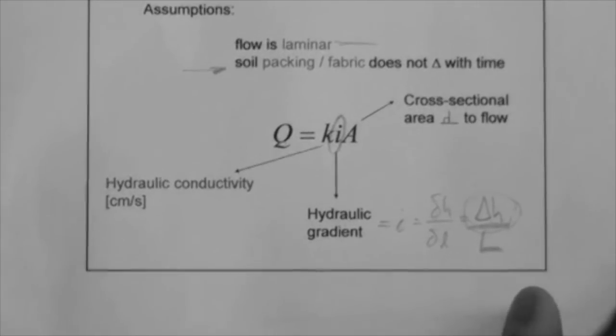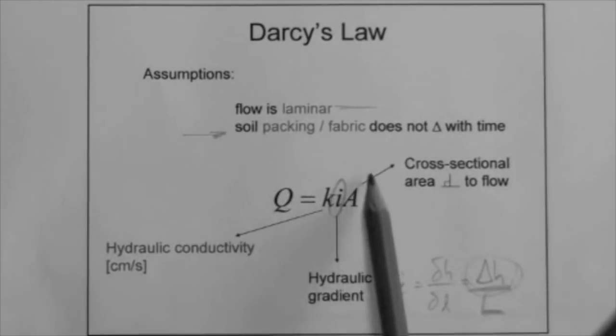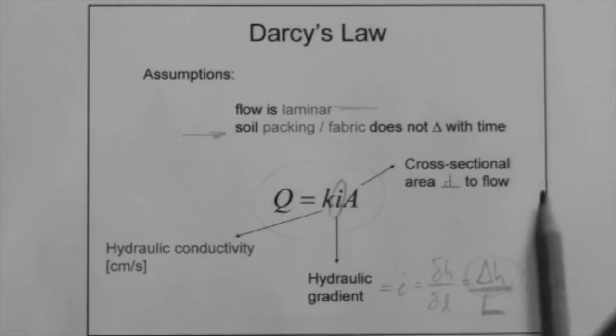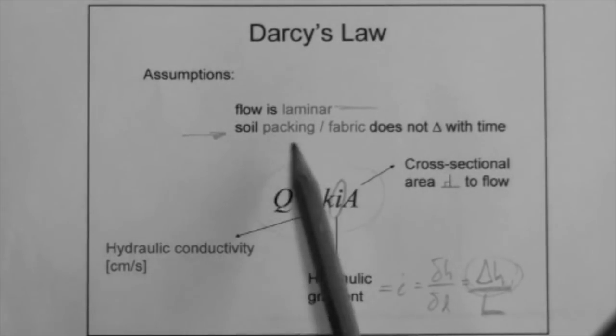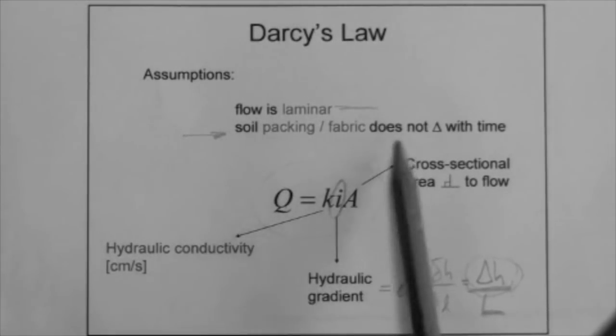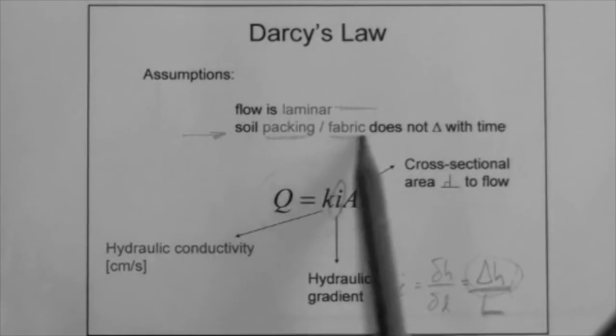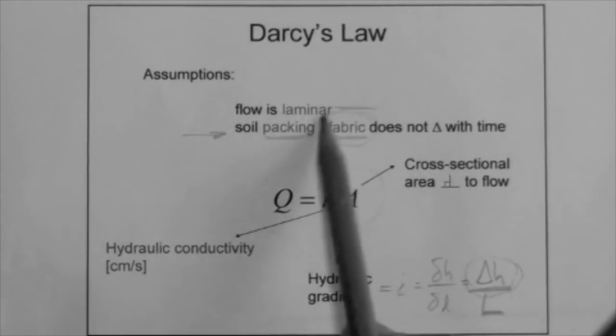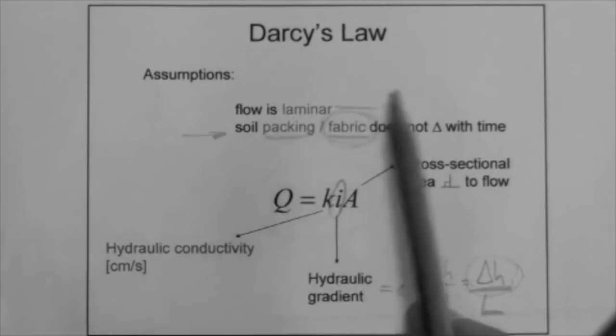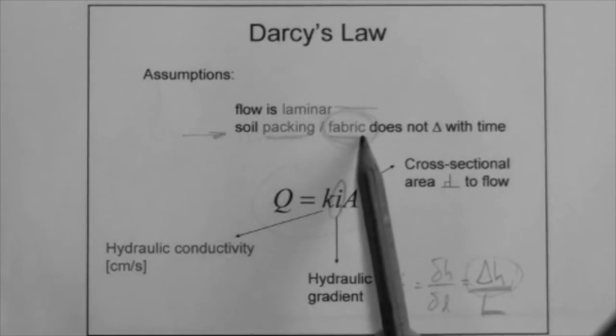So the assumption for the validity of this law is that the water doesn't change the soil fabric, or the packing for coarse grain soil. We can use the word fabric for both; it doesn't have to be packing. The fabric is the way the particles are assembled.